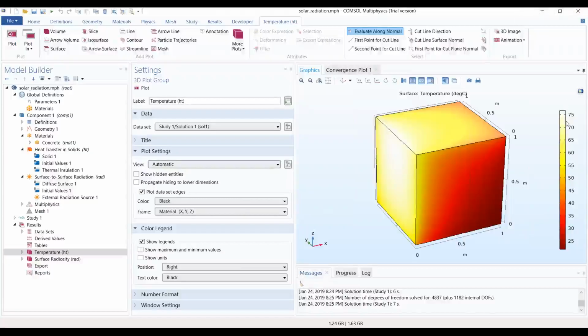And we see that now we get a really different temperature distribution. It's only 75 Celsius now, and it's due to the material property, the surface emissivity, which is no longer homogeneous, so more radiation is reflected, less is absorbed from the sun, and more is emitted on the ambient band. So we get a lower temperature, which is logical, but you can predict that only with different properties for the solar and for the ambient band.